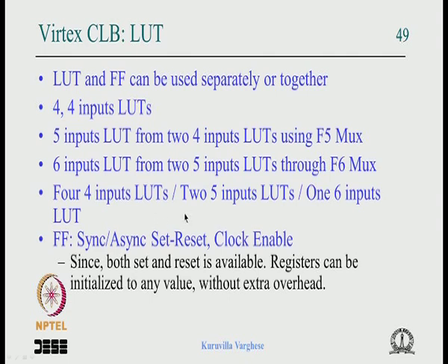Of course you can do cascading, and the flip flop has set, reset, clock enable. One advantage of set and reset is that you can initialize the registers to any value. You don't have to say at power on everything needs to be 0.